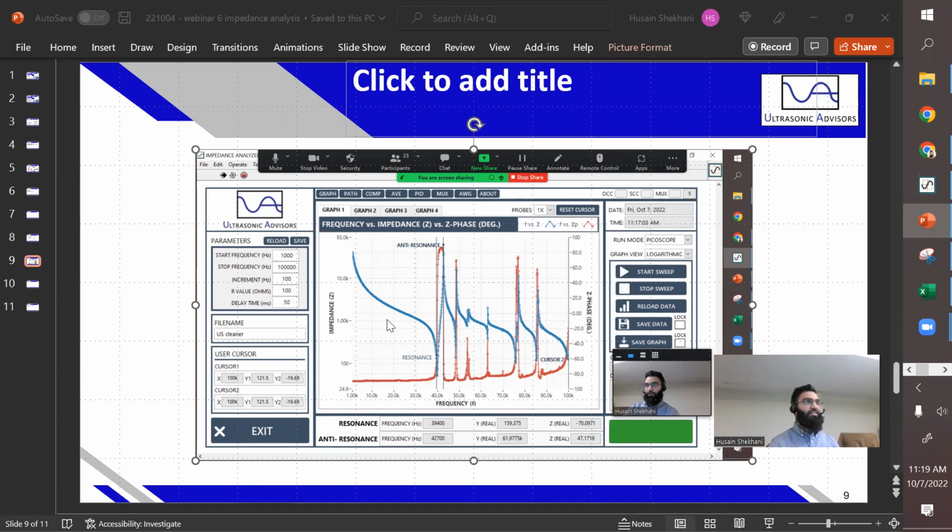For other resonances, how close is too close? I guess as an engineer, you get to decide that. Sometimes the unwanted resonances are bending modes, and bending modes have huge amplitude. Even if you're far off resonance from a bending mode, you still may be affecting your longitudinal mode. So that's up to the engineer to decide. Maybe you might say 1,000 hertz or something like that. Probably if you're within 2,000 to 3,000 hertz, that's not a big deal. Also, if it doesn't show up experimentally, but you see it in modal analysis, then you don't have to worry about it as much. But that's what I have to say there.